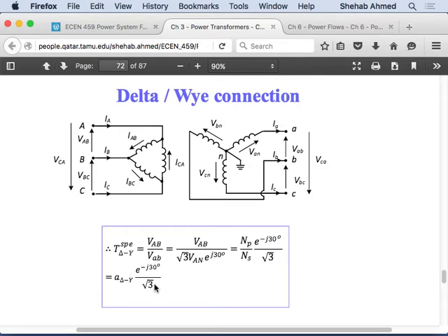If I tell you, no, you are given a 3-phase delta-star transformer with a terminal voltage of 10 to 100 kilovolts, then what is the actual turns ratio of the transformer? No, that's where you have to consider the square root of 3. It's 10 over 100 square root of 3. That's the actual turns ratio. That's this N primary over N secondary that you have to substitute in the T. The wording will define what you use, right?